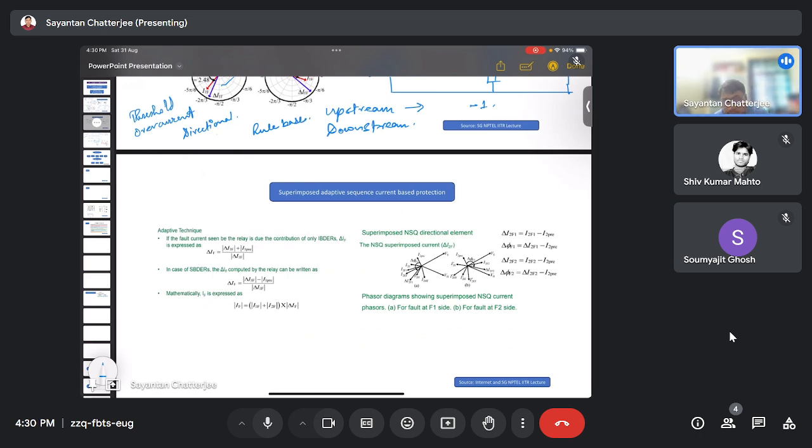So there you can get the magnitude and direction, which direction should be considered for which purpose, means whether the front side, based on this value, whether it is positive or negative, we can detect on which side the fault is. Now this was the case for one of the techniques, but we'll have to check whether we are designing adaptive protection schemes, right?